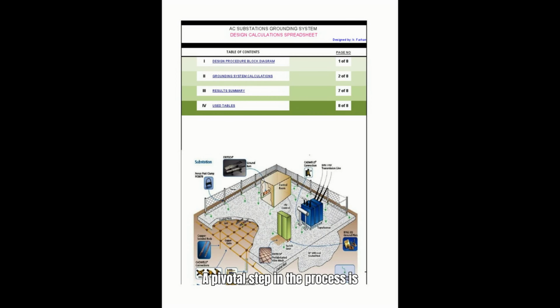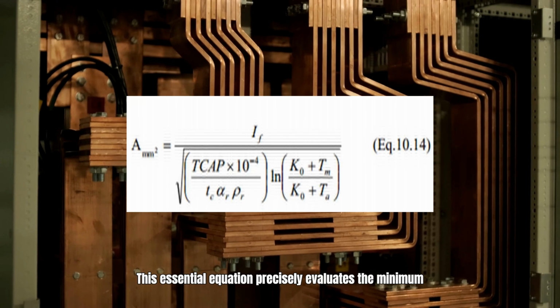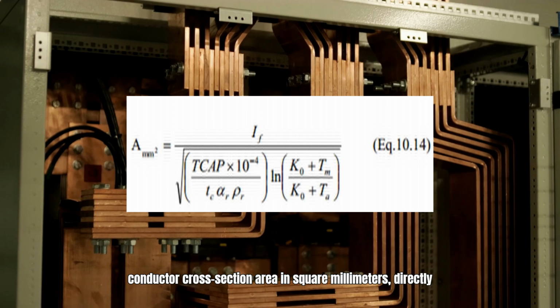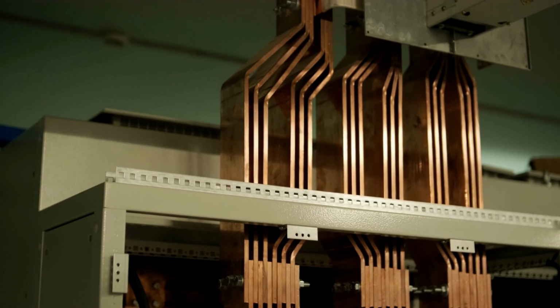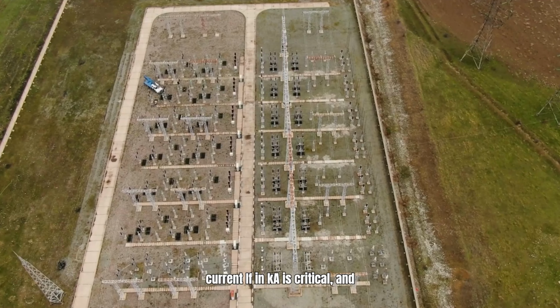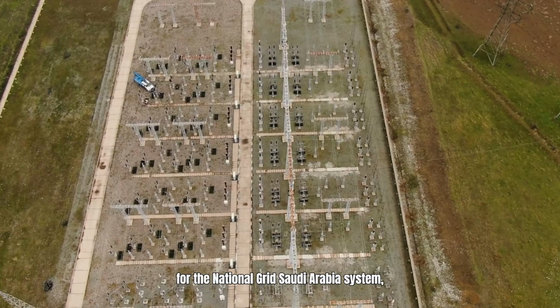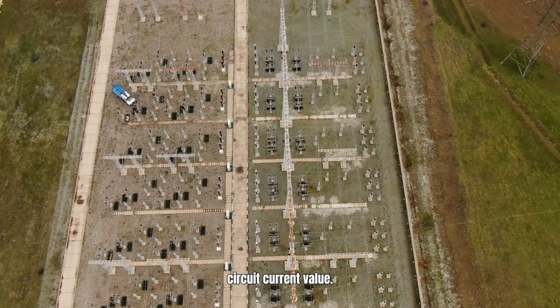A pivotal step in the process is calculating the minimum size of the grounding conductor precisely using equation 10.14 from established standards. This essential equation precisely evaluates the minimum conductor cross-section area in square millimeters, directly as a function of the maximum conductor current during faults. Among the variables, the symmetrical ground fault current I_f in kA is critical, and for the National Grid Saudi Arabia system, it corresponds exactly to the breaker-rated short-circuit current value.